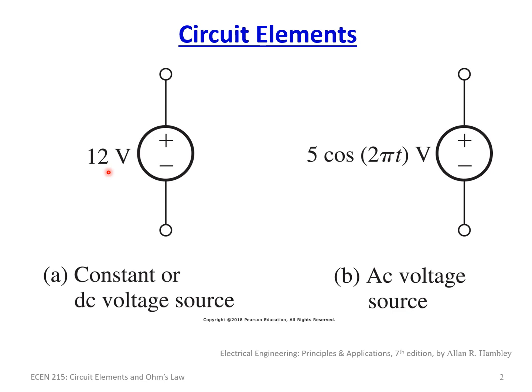Now, in the real world, that is not always the case. If you have a 12 volt battery and you take a wire and short it across, either the wire is going to explode and disintegrate, which usually is the case, or the terminals of the battery are going to disintegrate and blow up. I have actually seen a lead acid battery blow up, so it does happen. You can melt the terminals and pretty much destroy a battery. That's the real world. In circuit analysis, we view this as an ideal power supply, so it will provide infinite current at 12 volts.